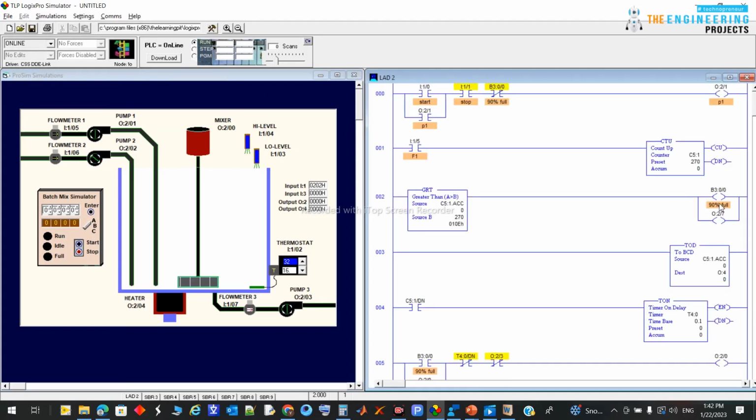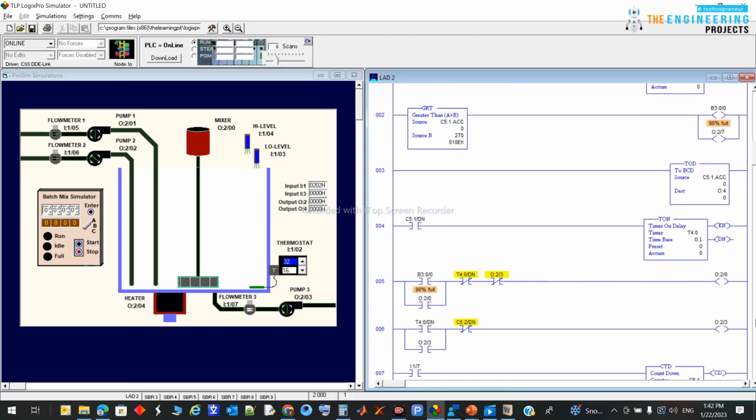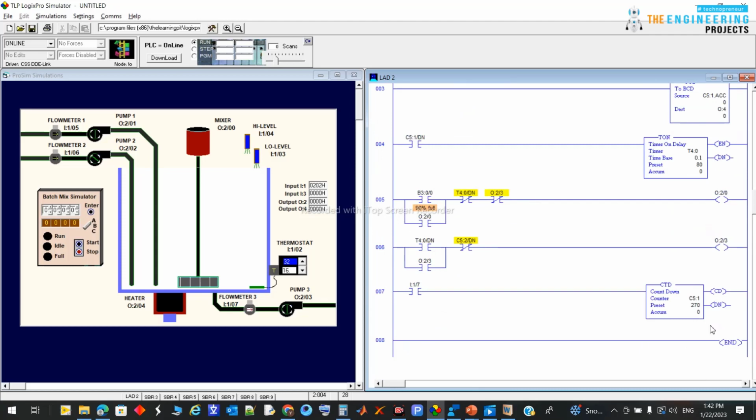Okay, so you can see here this setting will start from 0, preset is 270, which is correct, but the preset value here should be 80, and also this one is okay. So let's try again and run our program for the last time to see if it is correct or not. I know that I am increasing the time of the video this time, like 5 minutes, but actually let's learn together.